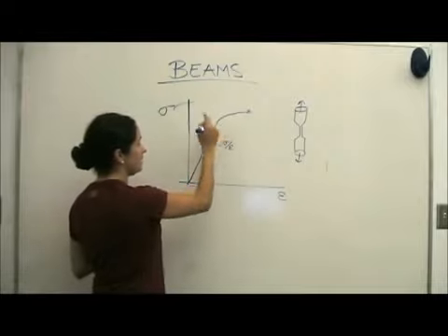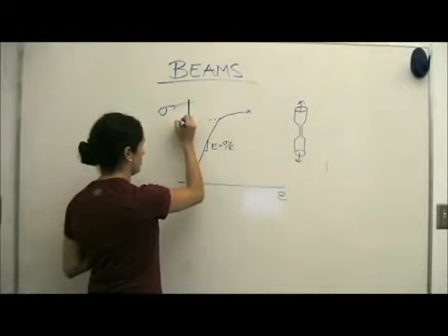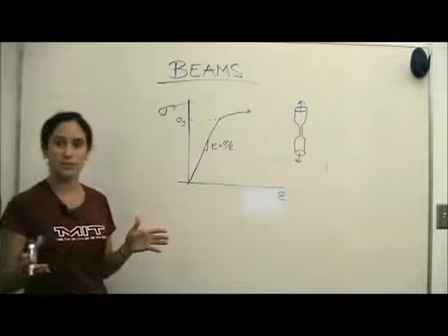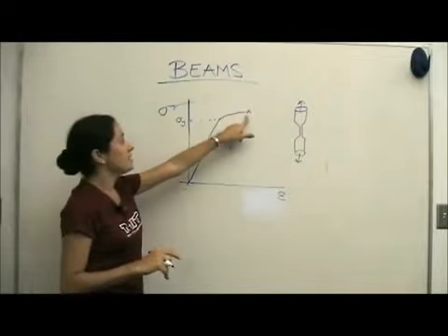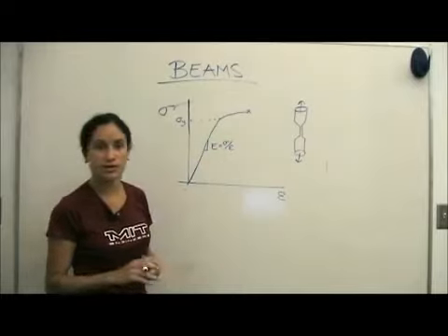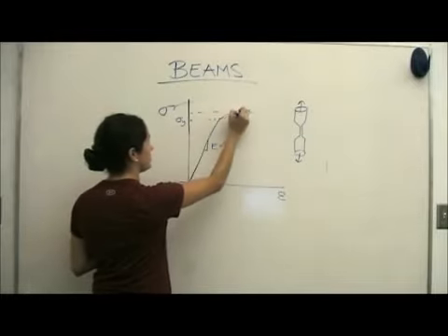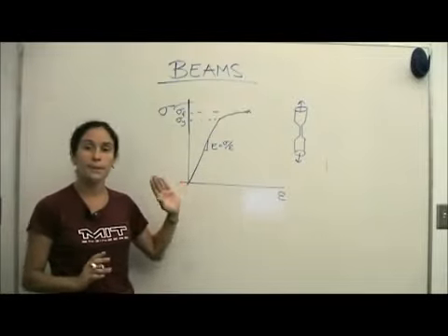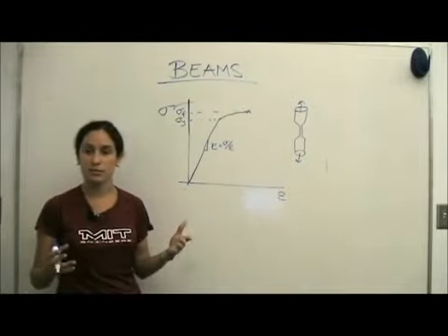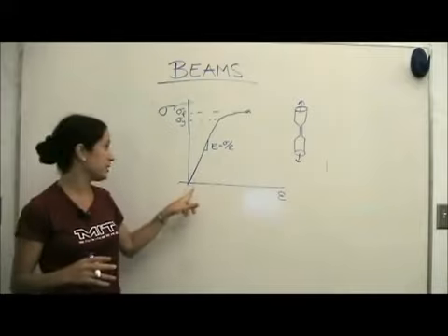When we see this bend, this is actually the yield stress of the material. It's the point at which the material stops behaving elastically and starts behaving plastically. This endpoint is usually the fracture strength or the maximum strength of the material. So we denote it fracture. This is a typical graph for a common material such as steel or aluminum. Most metals behave in this way.